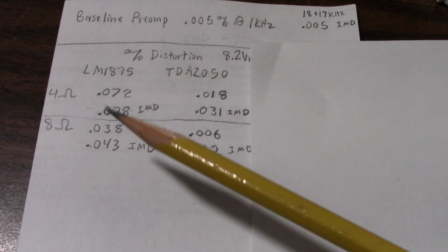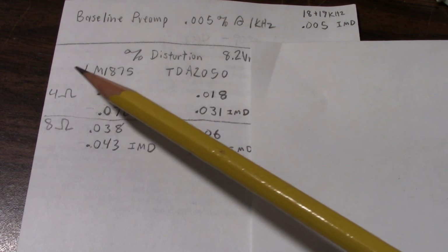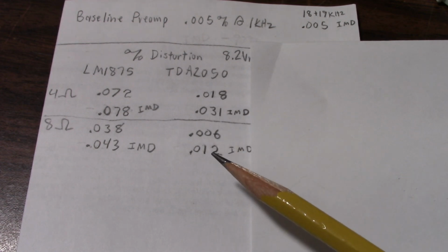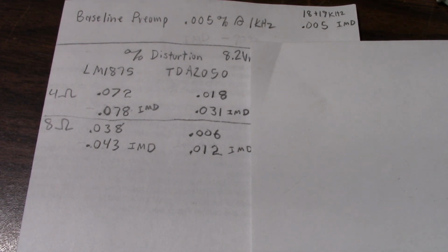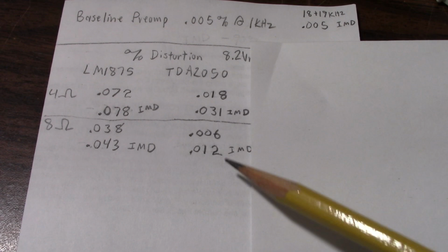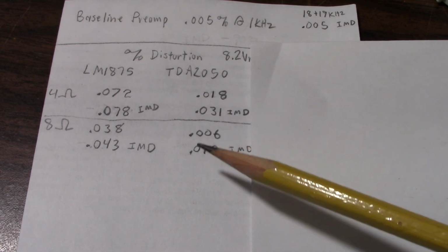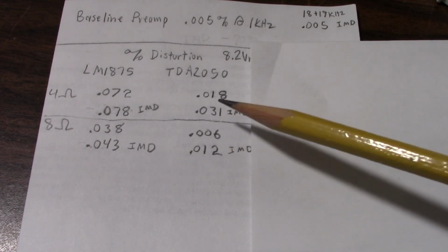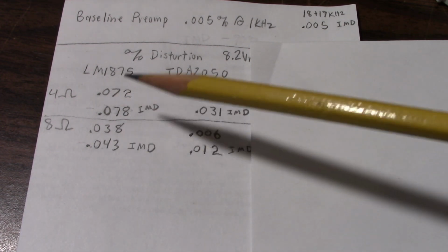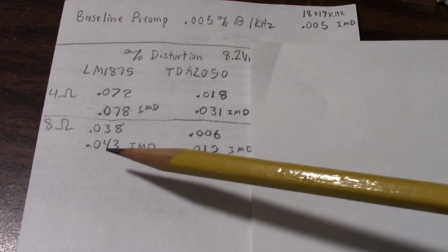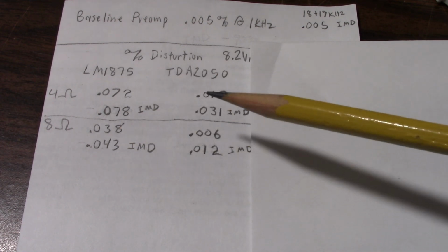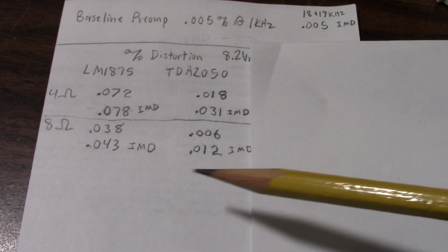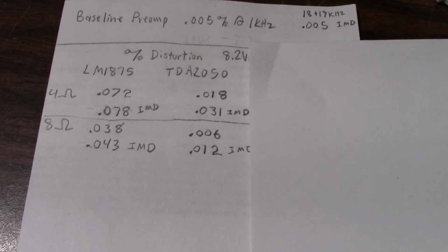Like I said in the last video, I would expect the LM1875 to do better than this one, but this chip really surprised me. Though, yeah, it still had some issues, like it needs help with stability using the Zobel network on the output, where the LM1875 was better in that regard. And the circuit design they used, you might give up something to gain something. That's just the way it works out.